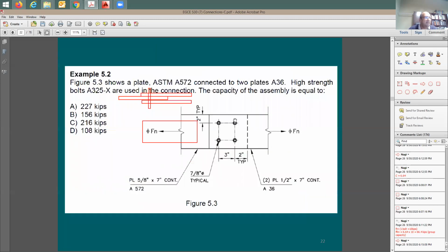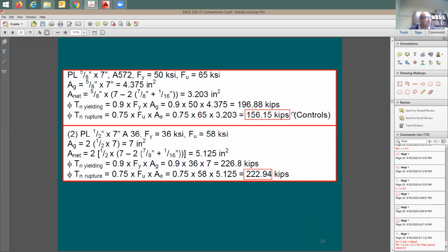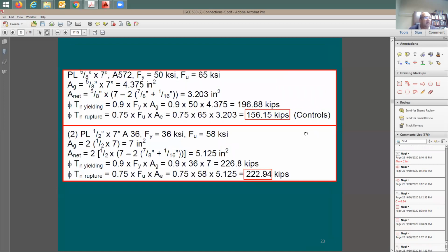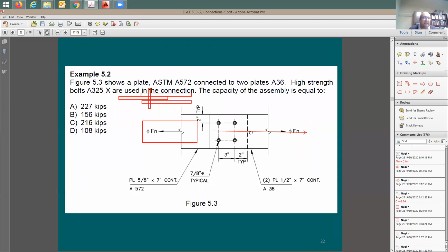Let me go to this example here. I have 4 bolts. The force was right in the center. It was split evenly among these bolts. So now let me look at the strengths of these bolts. It says here, Rn is going to be equal to C times rn, so in this case, C equals 4. I have a total of 4 equivalent bolts, and in reality, I have 4 bolts. The reason that I don't have any reduction is because this force is concentric with these 4 bolts.